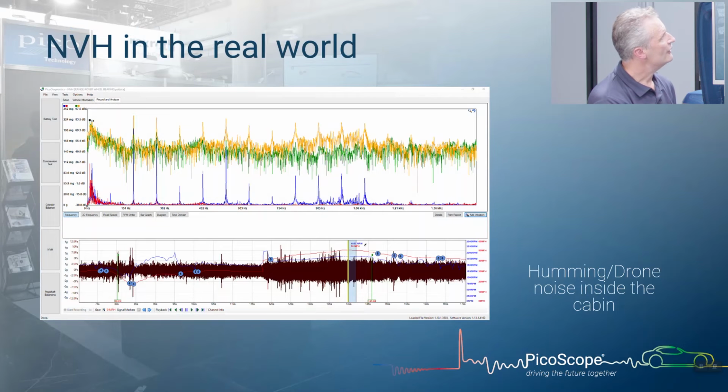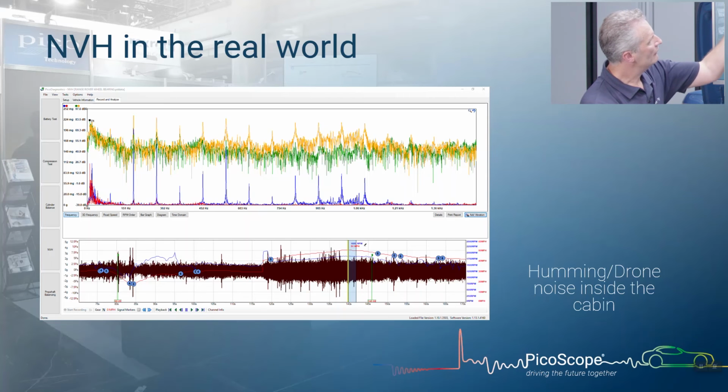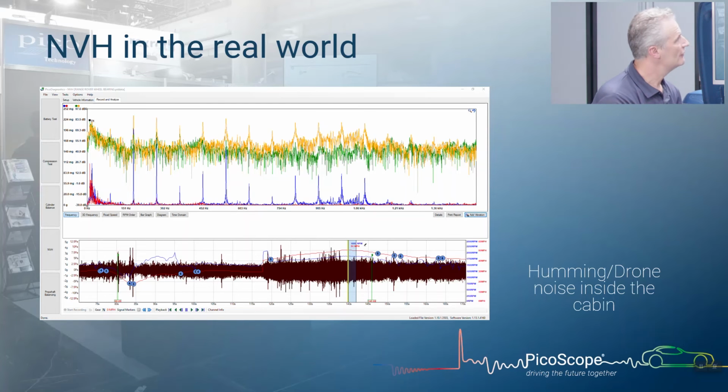All right, next up is wheel bearings, NVH in the real world, looking at bearing diagnosis, not just wheel bearing, but this is a classic example of a bearing. I just want you to notice the harmonics here, multiple spikes. Channel A and channel D are connected to the same component. They're actually one accelerometer connected as an accelerometer and then also connected as a microphone. This is a way in which we can cheat slightly and listen to our accelerometer as a contact mic.